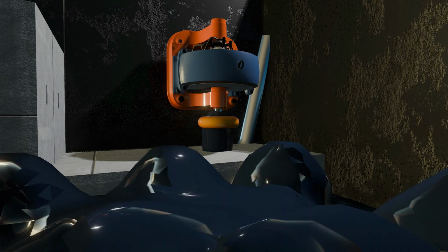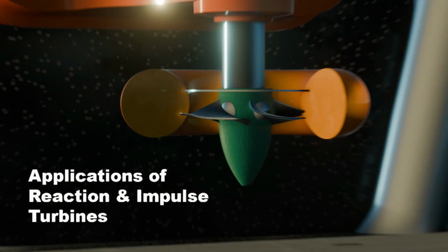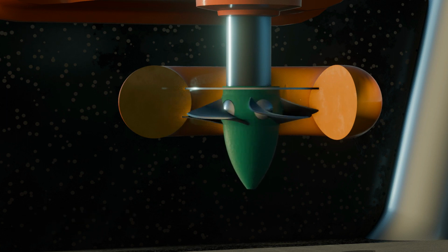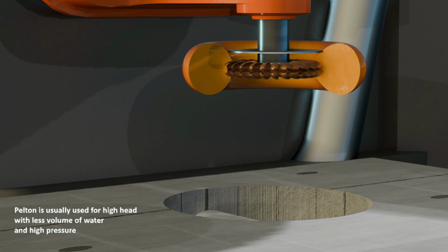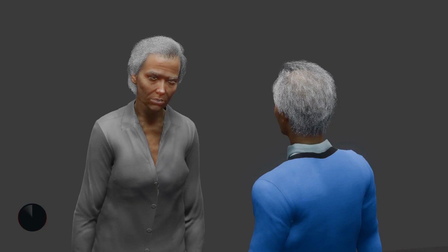So based on the earlier calculations, it can be said that the low head site would need a physically large Archimedean screw or Kaplan turbine inside a turbine house. And the size must be large enough to physically discharge such a large volume of water with a relatively low pressure across it. While the high head site would only need a small Pelton or turbo turbine the size of a fridge. That is because it only has to discharge 5% of the flow rate of the low head system under a much higher pressure.